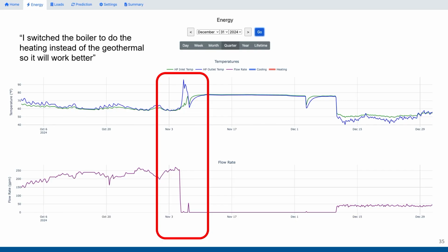I'm Jim Snyder, and I'm just a simple geothermal installer, right? But we went to this school, and of course, I'll use some names. So one company was trained, put in the things. Another company did the design. Honeywell does the energy management, and it's fragmented, right? They asked me to come and look at a couple of things. The interesting thing, I think, why this is so important is that these guys are blowing up these machines, these heat pumps. There's not enough flow going through the units and those types of things.